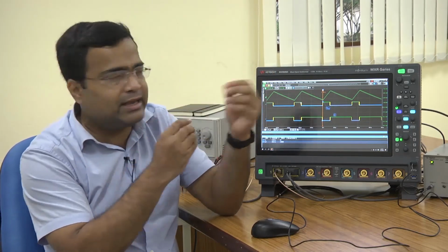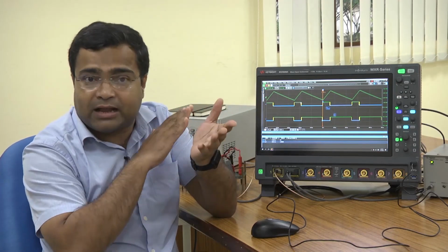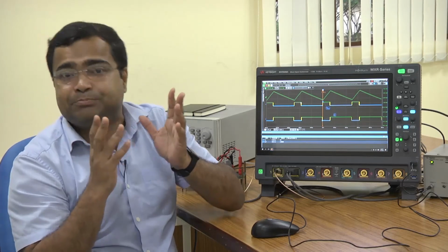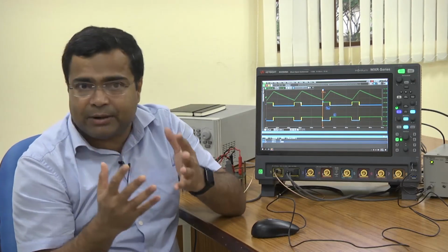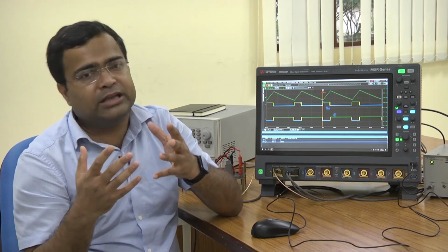Suppose, here we are using a mixed signal current mode control where the peak current reference is coming from the digital logic, and we are using a D to A converter. But we can also see the digital value of the peak current, and that can be analyzed by this digital channel, and you can figure out if any of these bits goes wrong. So you can easily debug the problem in your design and rectify it. That's why I would say the mixed signal oscilloscope is very useful, in fact necessary, to debug, test and validate a digitally controlled converter. And I think that was the purpose of today's lecture. Thank you very much.